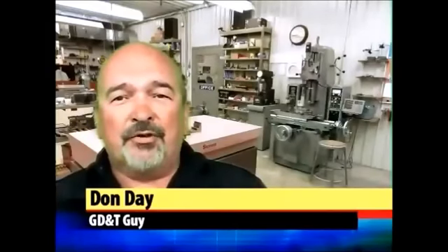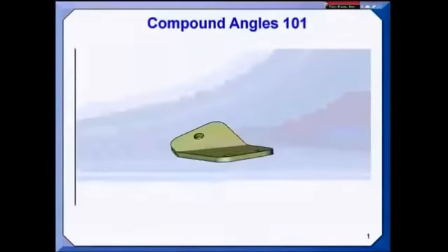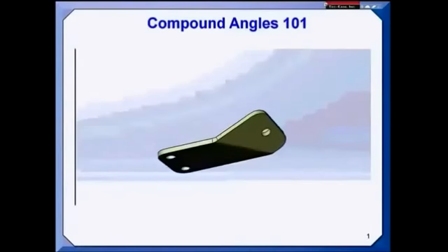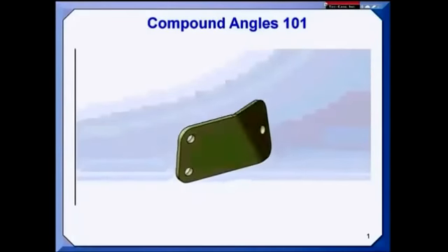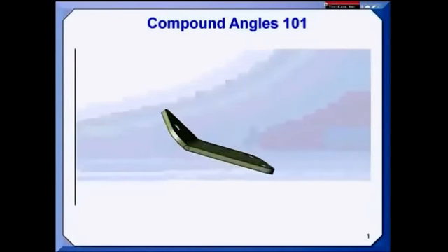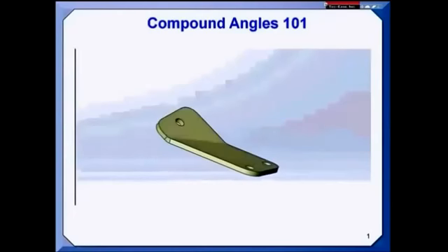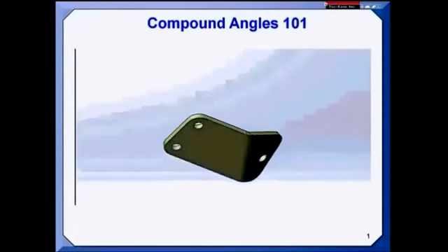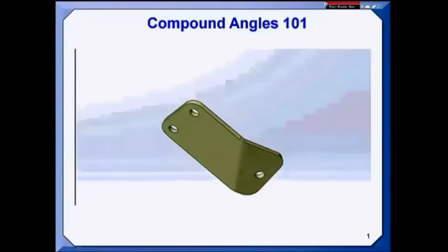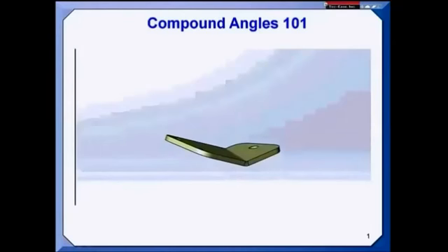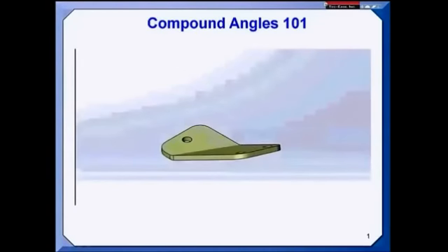Here's another tip regarding how dimensions are placed on a drawing. A metrologist friend of mine calls it Compound Angles 101. Keep in mind when applying basic dimensions, unlike directly toleranced or plus-minus dimensions, that it really doesn't matter how they're placed on the drawing from a design intent standpoint. In fact, many companies now are leaving the dimensions off and letting the supplier query the model.